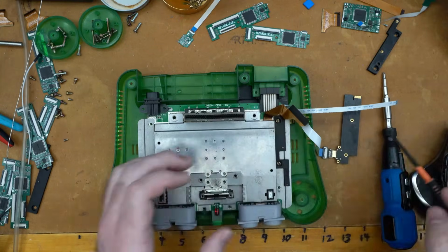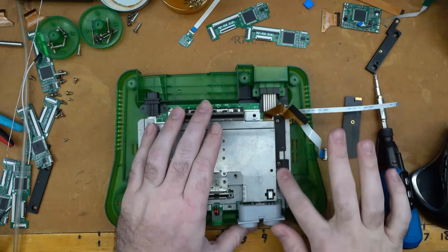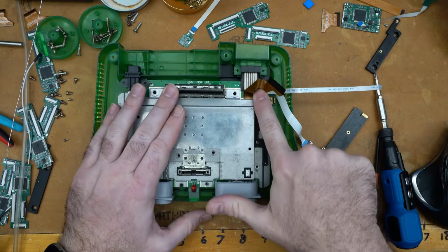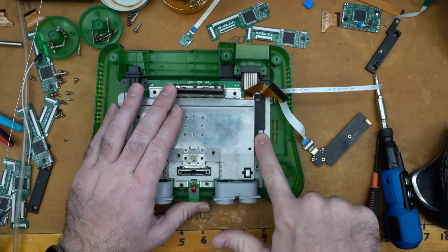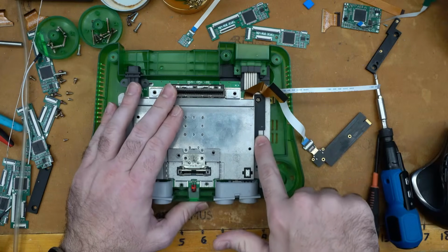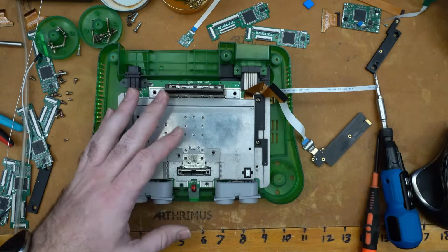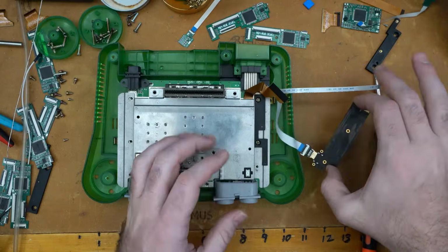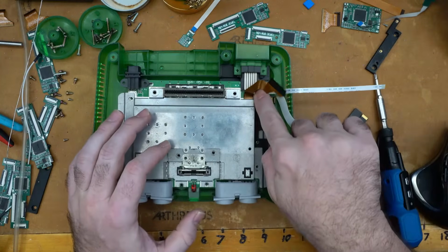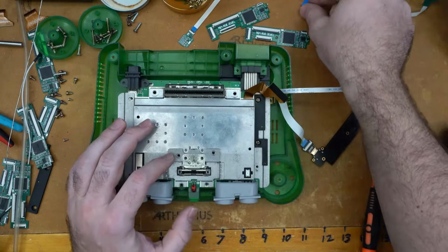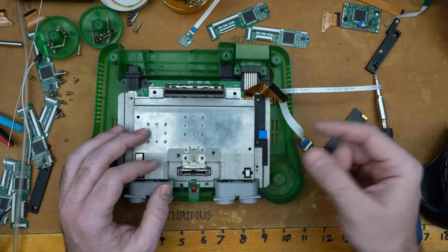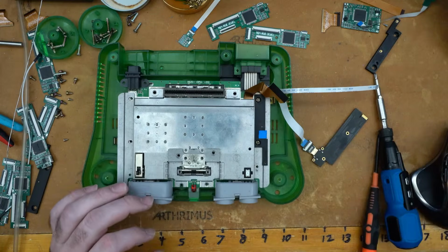Okay, so our new 3D printed bracket is in place. You want to check with your finger just to make sure that there's no burrs or anything like that sticking up from the screw heads, because the clearance is really thin on this thinner 3D print. So you don't want them puncturing the solder mask on the Retro GEM. So just make sure there's no sharp edges coming up. We take our thermal pad and we just pop it right in here in the little notch there.